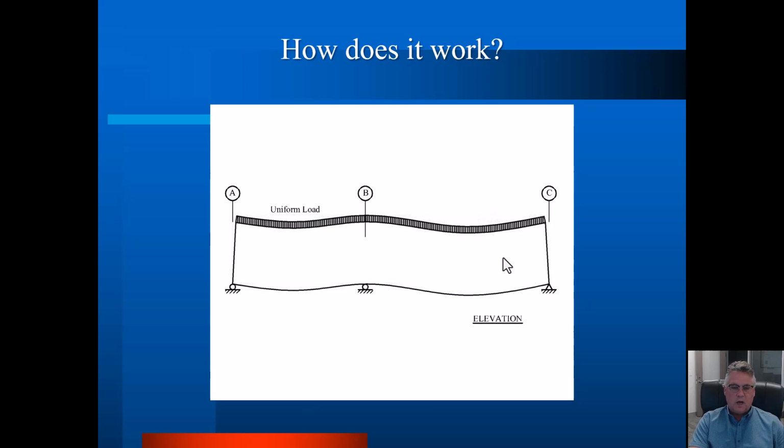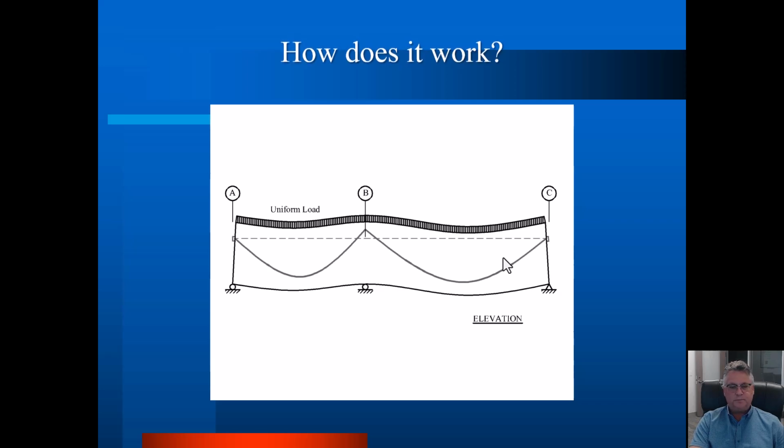Concrete wants to deflect. Every material wants to deflect. Concrete has a little bit of a worse deflection issue than other materials in that it tends to continue to deflect under creep and shrinkage. So that's a little bit of an issue for reinforced concrete. Pre-stressed concrete basically solves that deflection problem. It solves a number of problems, but one of them is the deflection problem. And that you can kind of visualize here.